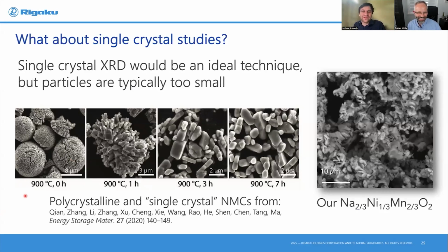Batteries going on fire, absolutely a big issue. And on safety of lithium-ion batteries, the main component that is dangerous there is actually the organic electrolyte. The organic electrolyte is what catches on fire first, frequently. You don't typically have lithium metal in your cells, but you can have small dendrites of lithium that form, short the cells, and catch on fire.